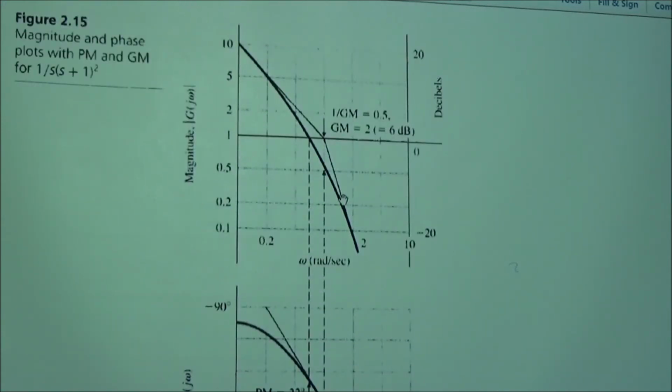And your end plot for the magnitude will have a slope of minus 60 dB per decade. That's how fast that magnitude plot goes down. So because you have 3 poles, each of them minus 90 degrees and minus 20 dB, 3 times minus 20 gives you minus 60 dB per decade at the end.